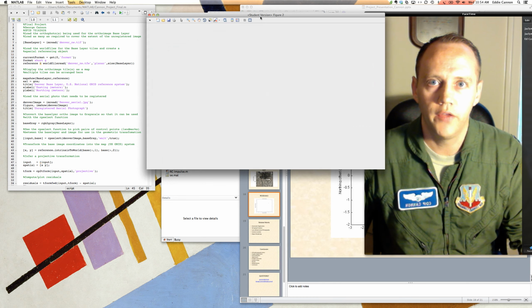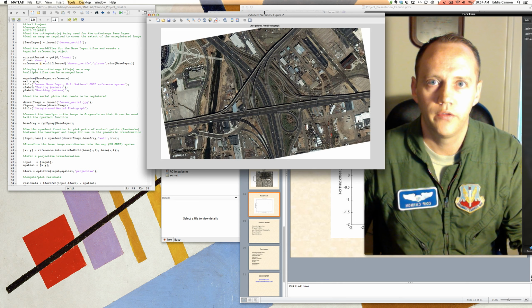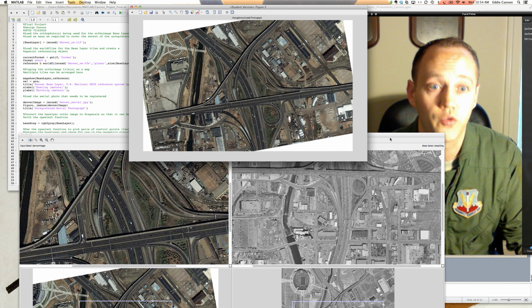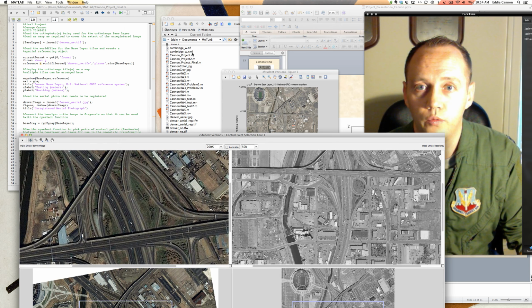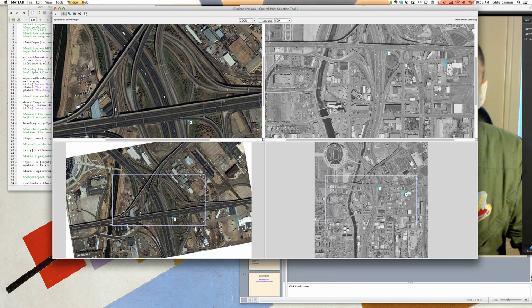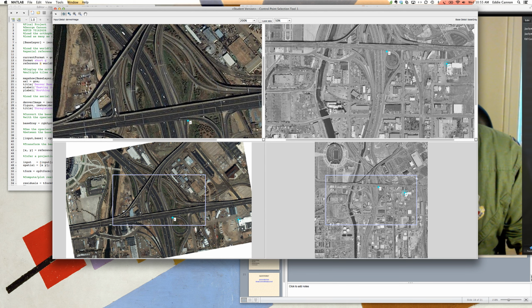When the file is run, the first image that is generated is the map base layer here, labeled Figure 1. Once that pops up, next is loaded in the image that we're trying to register to that map base layer, Figure 2. Once those populate, then the control point selection tool pops up. Based on the type of rectification that we have here, you need to select at least 4 points in space in order to be able to get the georegistration to work correctly so that the map space can accurately perform the translation, since it's dealing with a complex problem. So 4 features in order to be able to calculate the 9 coefficients required to do this transformation, and that's discussed in the paper.